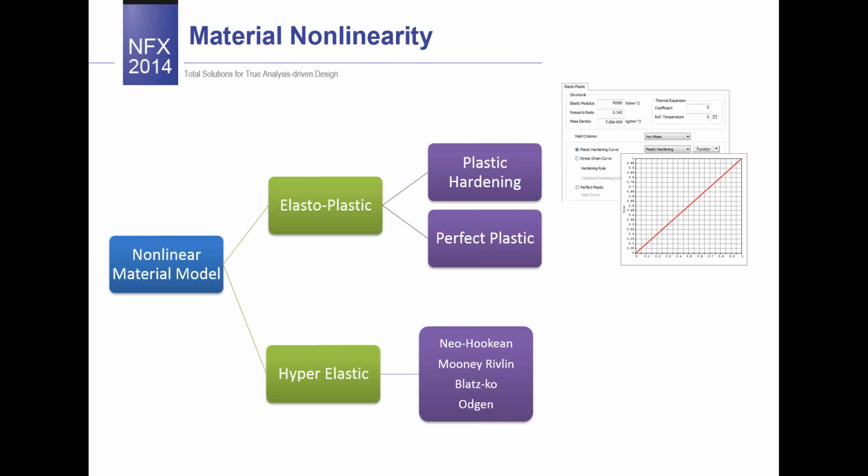The second model is the hyperelastic material, which is still an elastic material, and this means that the specimen will return to its original shape after the force has been removed. The difference to the linear elastic material is that in hyperelastic the stress-strain relationship derives from a strain density function. As an example, elastomers like rubbers are often modeled using hyperelasticity because usually they have large strains at small loads.